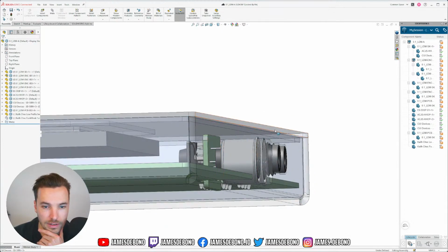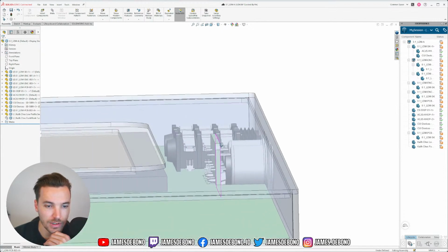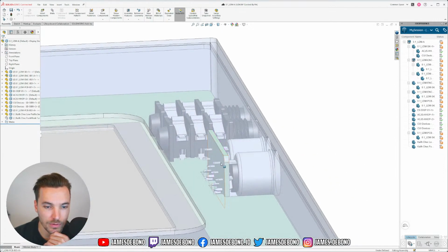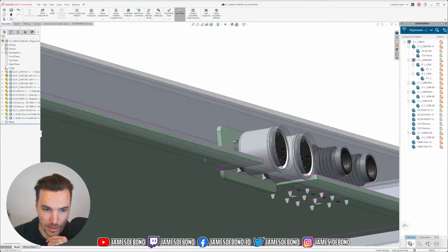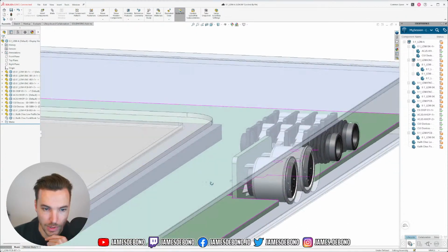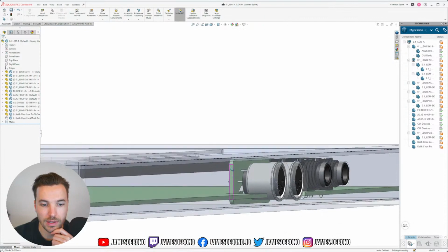Now, I had a couple of ideas which I mentioned in the last stream. One was that I would have some kind of brace here that is like a metal piece that sort of triangulates this. So the metal piece solders down into this PCB, and then you would put a screw in through this face and into the metal bracket behind it. That would mean I would need to have 2 brackets and 2 screws at least.